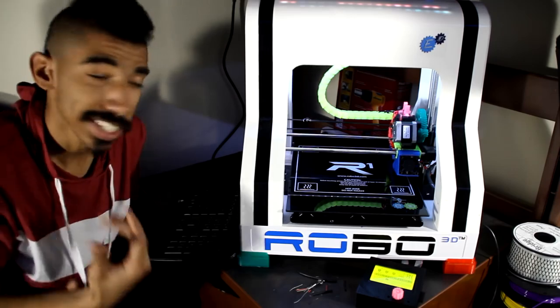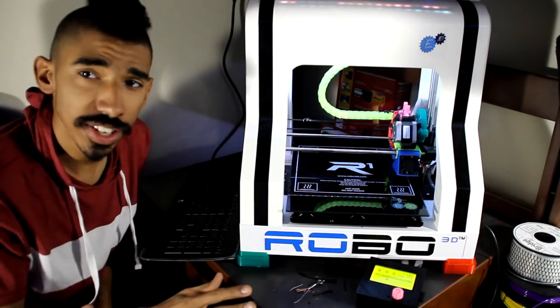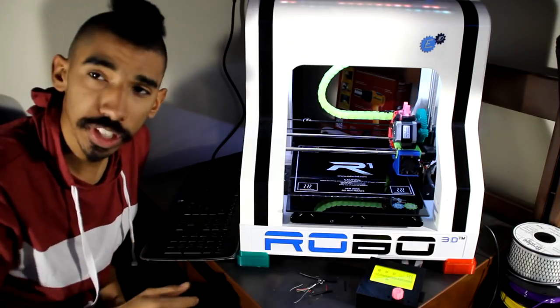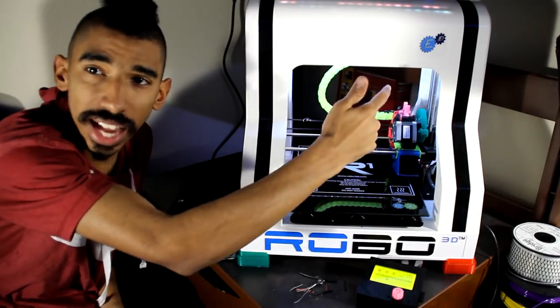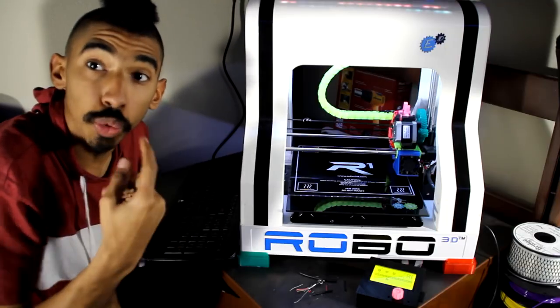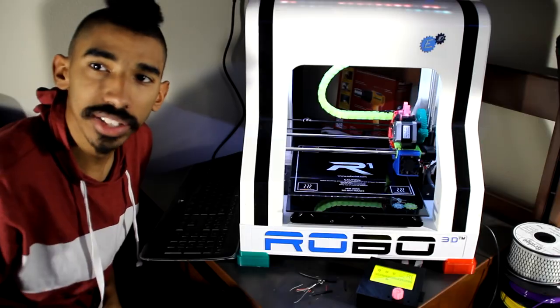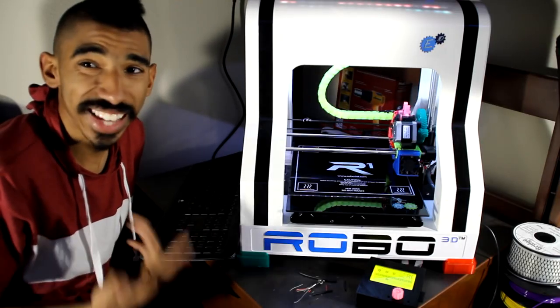This one I can't necessarily show you, but it's called an M25. It pauses any SD card print that's being implemented. I put this in my startup G-code. After I'm done with the Z probe, I raise the Z-axis and then I run an M25 so that it waits for me to resume the print so I can put the bed topping on there. So an M25 will pause an SD card print. You can run it from the keyboard while you're running a print, but it's got to be printing from the SD card.